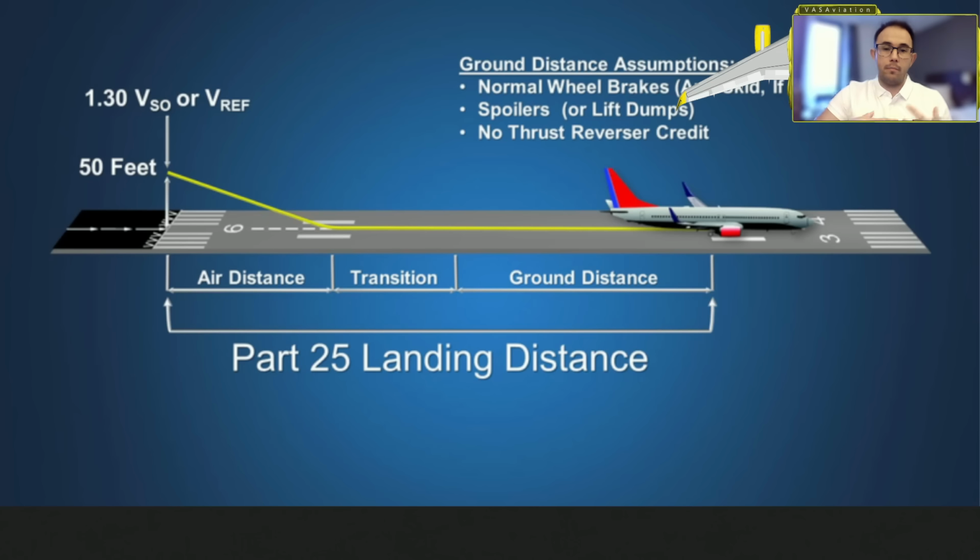So in this video, I'm gonna try to explain, especially for those that got this thing wrong or maybe don't know what this is, the approach categories and how we calculate and how we know which approach category our airplane is. Okay, so first of all, we're gonna talk about what the approach categories are. Depending on what approach category your airplane is, you're going to choose some parameters during your approach, especially the minimums. The higher your approach speed is, the higher your minimums are going to be. We have 4 or maybe 5, but let's say we have 4 approach categories.